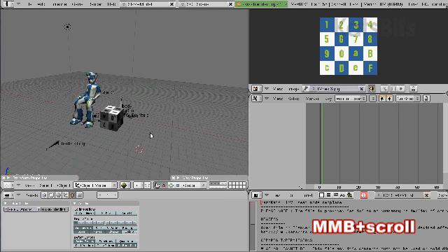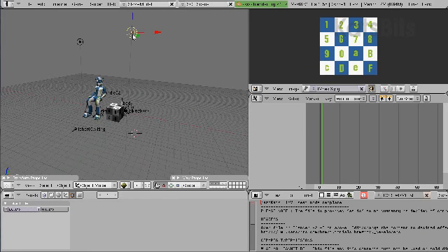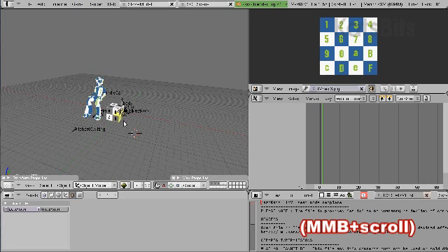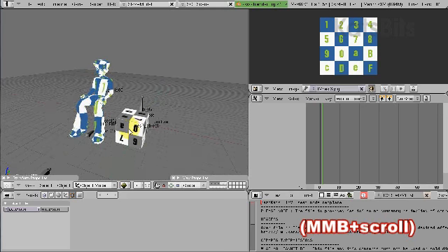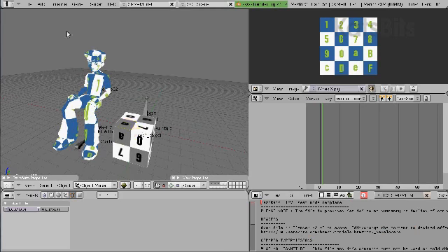If we scroll out, middle mouse button scroll, we can also do that with the light objects. Now, because there are several objects in the scene, we can select them, multi-select, by holding the Shift key down whilst we click with the right mouse button. So we selected one, right mouse click, hold the Shift key, right mouse click again, and you've selected two objects. Press the M key and move that to the layer that we've been using to move every other object to. Once we move those lights out of the way, the scene becomes flat lit.